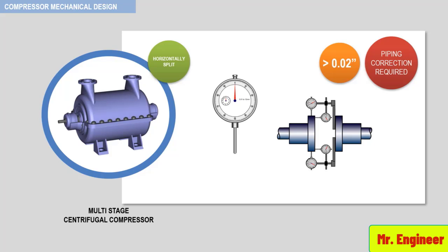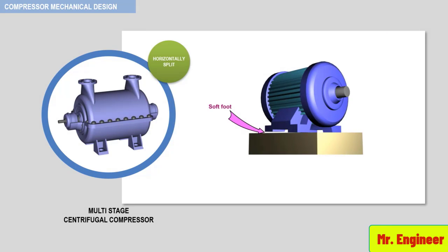The cause of soft foot is that the plane of the support is not parallel to the plane of the foundation, and a gap exists between the foundation and support foot, as depicted here, a soft foot for the compressor motor.